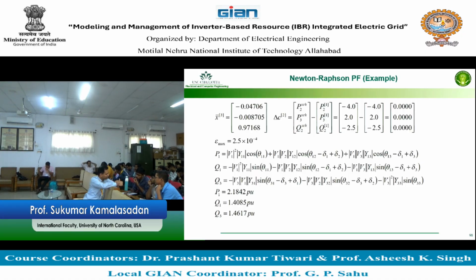Run an optimal power flow just like that and see what will be the reduction. It's a first step, assuming that the EV charger is following it, right? So that's the first step. After that, how to implement it? To implement it, this has to go to the EV charger controller, and the EV charger controller should follow, like what we are doing, implementing.